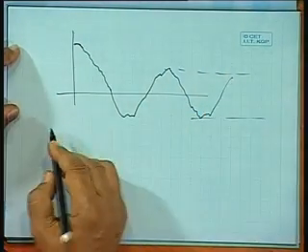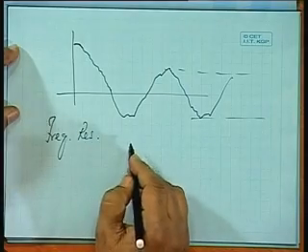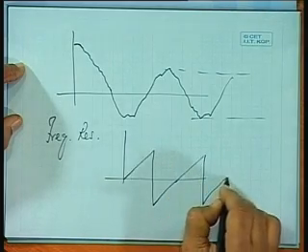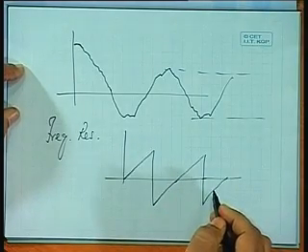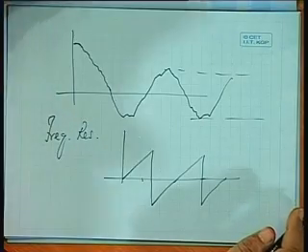then there is an advantage of using the frequency response technique. We have studied so far the response due to a particular frequency. Now, if you are giving a periodic function as input, is it possible to resolve this into a large number of sinusoidal functions? Our aim here is to resolve that and then find the response corresponding to each elementary sinusoidal component, calculate the response due to each one independently, then use the superposition theorem and take the total sum. That will be the response due to any periodic function.